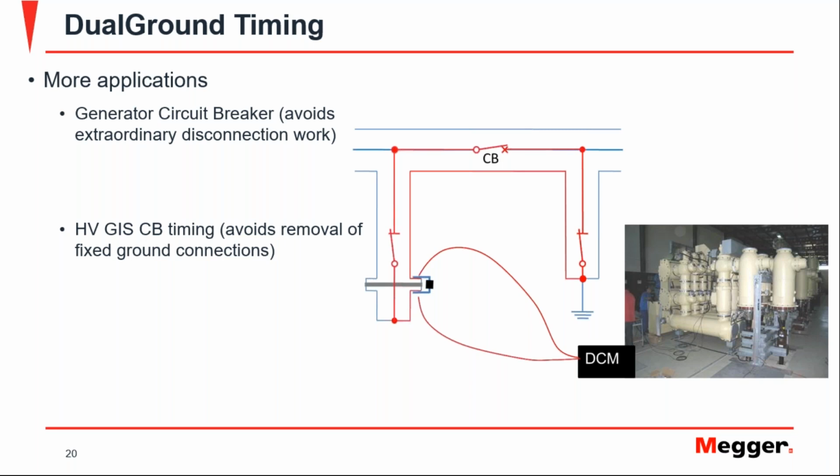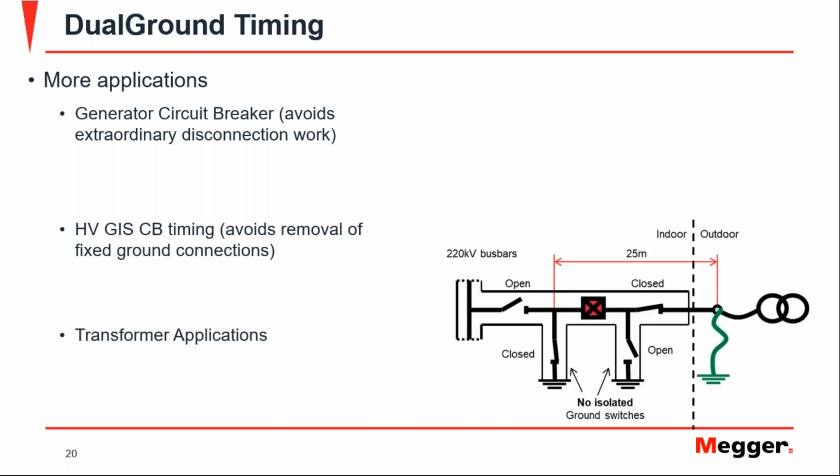Again, not safe, because the circuits next to the one that you're testing are going to have a lot of capacitive coupling with the point. So you are introducing a safety hazard. So with this DCM technique and one more accessory, you can test very easily, very fast.